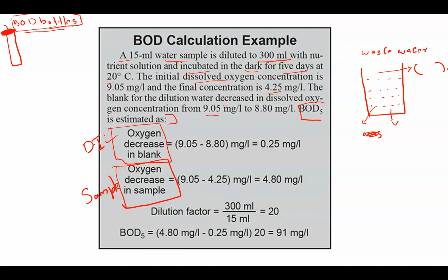If the sample has a high organic load, then dilute it with O2 saturated distilled water. So if your solution is very concentrated, you have to take DI water, but you should make sure that your DI water is saturated with O2. So how do you saturate your DI water? You have to aerate this DI water and make sure it is completely saturated, so that no further oxygen is able to dissolve in the water. Then you pour this saturated DI water into your sample to dilute it.